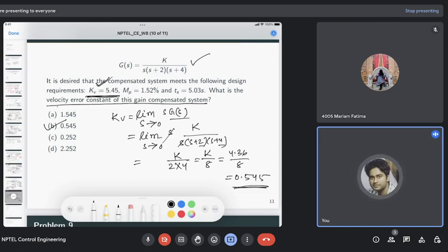Okay, because only just placing that pole will hinder this dominance effect, and also, as you already know, adding a pole will make the system unstable because it will pull this root across to the right. So that's why in the lag compensator we need both a zero and a pole very close to each other, so they will cancel in effect, and the angle contribution will also be very small. If the angle contribution from this compensator is very small, then we know that the transient response will not vary much after adding the lag compensator.